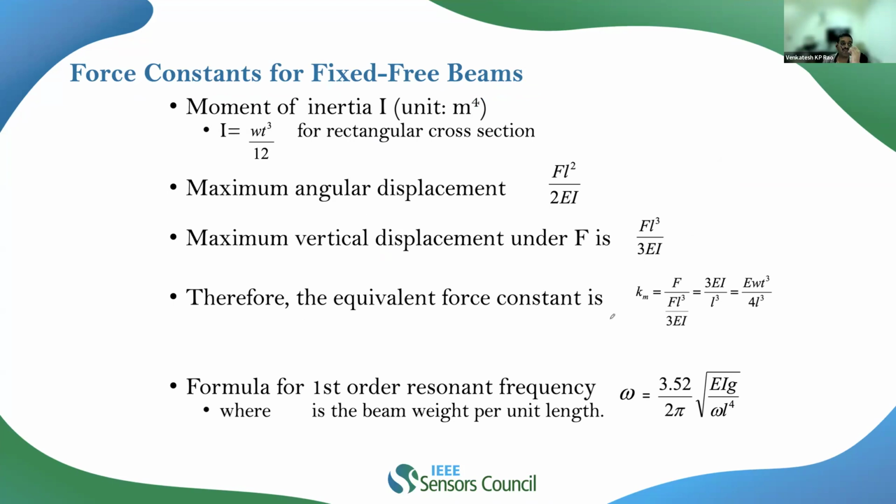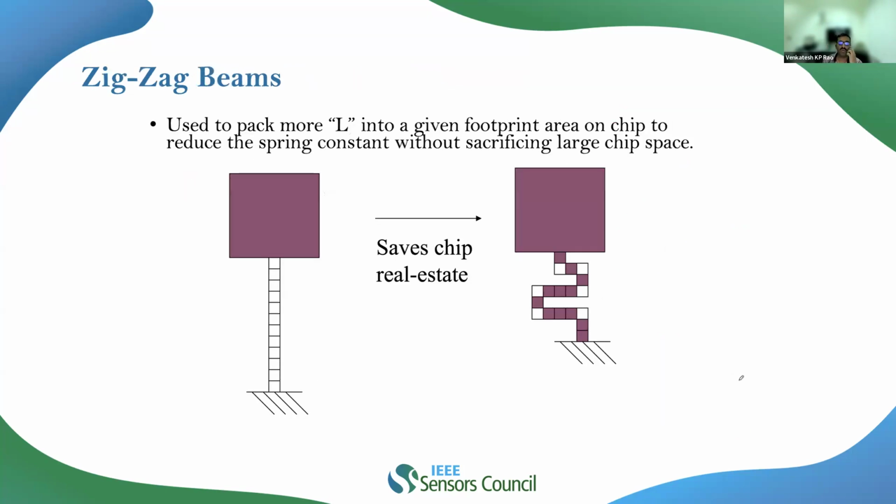So this is an important slide for all of you. Whenever you take up any of the beams under consideration, the first and the fundamental things are this. For the simple cantilever, the vertical deformation you get will be this. And then the natural frequency associated with the simple cantilever will be around 3.5 divided by 2 pi times the square root of EI divided by rho A L to the power of 4. This is the fundamental natural frequency that you get.